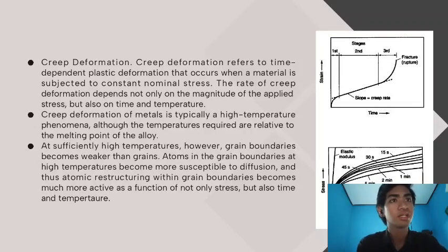Metallurgists in the early 1900s also defined a temperature at which the strength of the grains and the grain boundaries are equal. It is called the equicohesive temperature, or ECT. The ECT is affected by material characteristics and the loading condition. There are many variables that affect the ECT, and the quantification of an actual temperature is possible for only a specific set of conditions. The usefulness of the ECT in practical terms is limited.